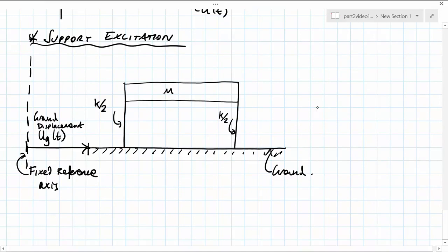One of the major applications of structural dynamics is in the earthquake analysis of structures. Earthquakes do not directly apply forces, they cause ground motion, which is typically lateral in nature. The combination of the structure's mass and the lateral ground motion is what develops a secondary inertial force that we refer to as the effective support excitation. To measure this, consider the following single degree of freedom structure. This structure consists of a rigid mass attached to two columns with stiffnesses of k/2 each. The structure is only allowed to displace laterally, so it is still a single degree of freedom structure.